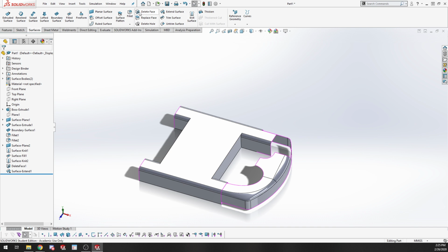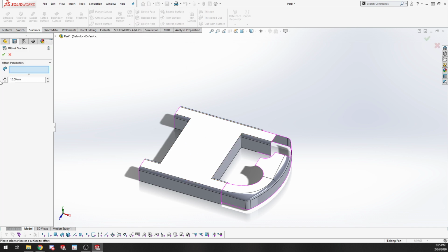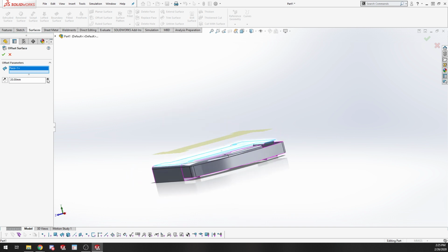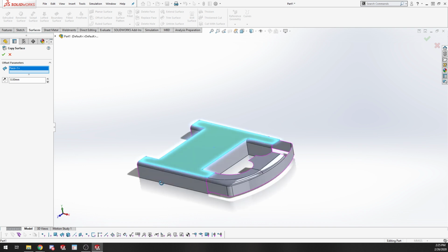edges. Let's see, what else are we covering? I guess the only other one that we should cover is the offset surface. So sometimes you have to use several surfaces or a surface several times to create different kinds of geometry. If I had my steering wheel model on, downloaded onto my laptop, I could pull it up. But with offset surface, I can go through and just offset this to a certain dimension. I guess I could translate that surface to the bottom of the part.